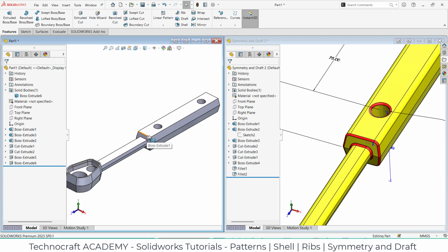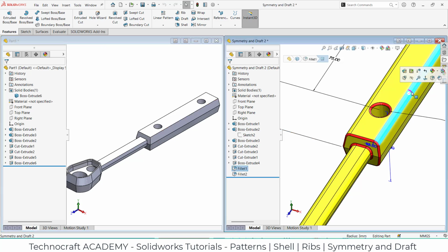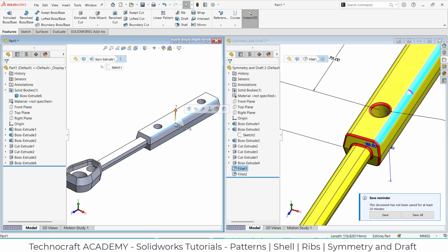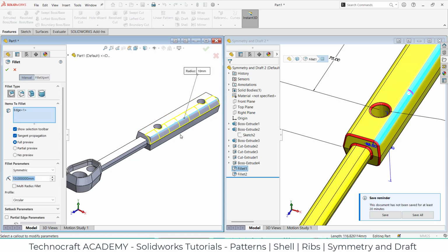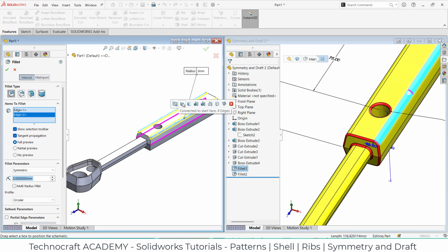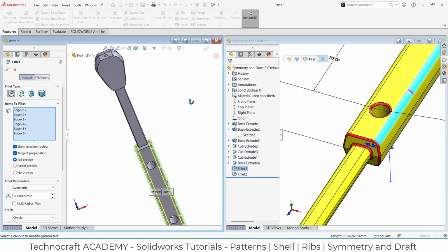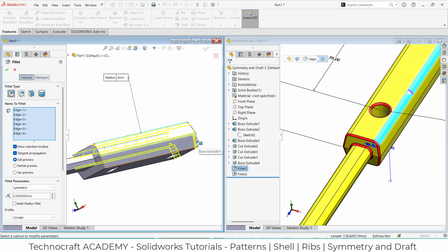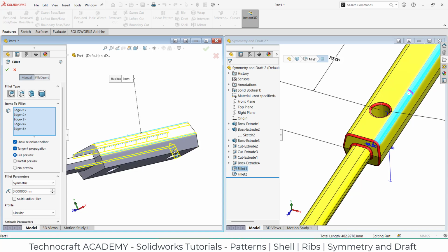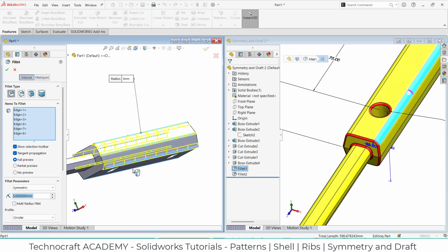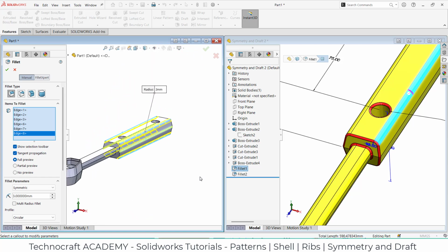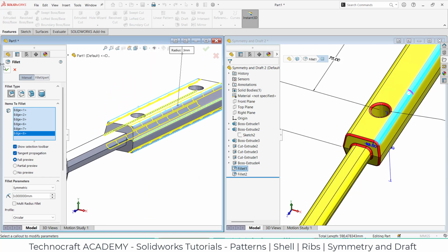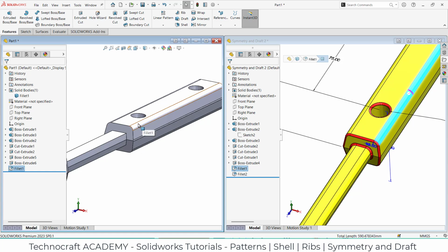Shortcut is, okay, first make this fillet. So how much is this? Is 3. Just click on this and click on fillet. Just enter 3 here. If I select the next edge and switch for this one, it will automatically select all the corners. It is taking this also, not recommended. Okay, so this is fine. Now green check.